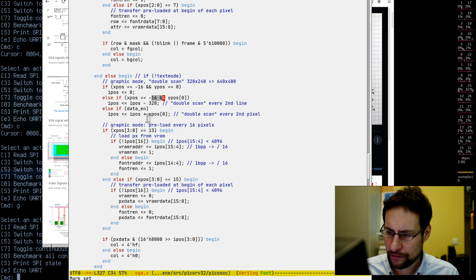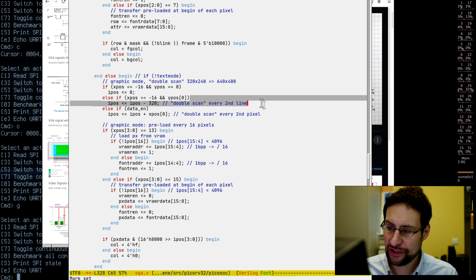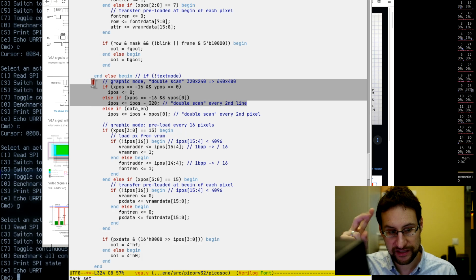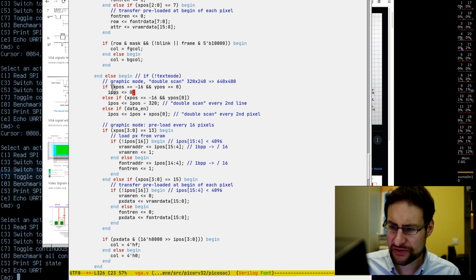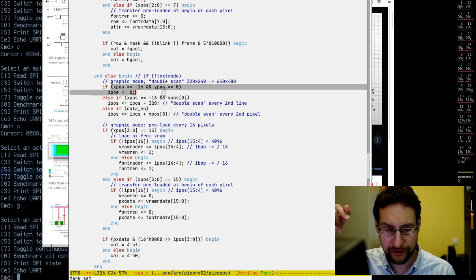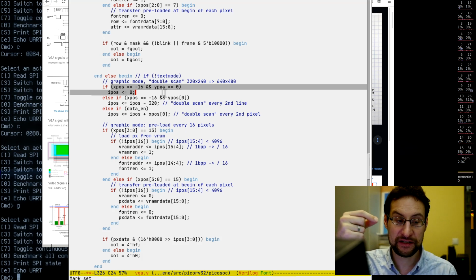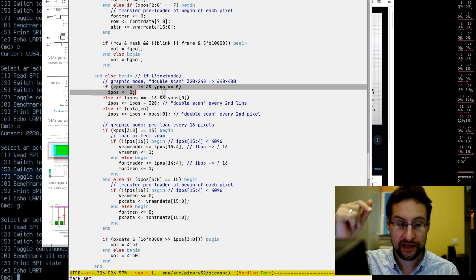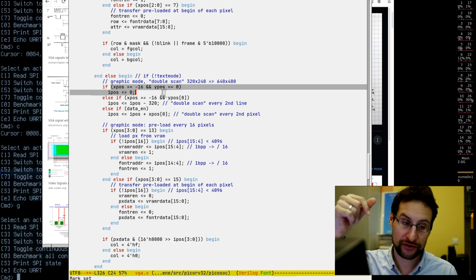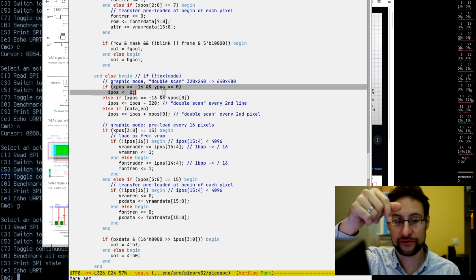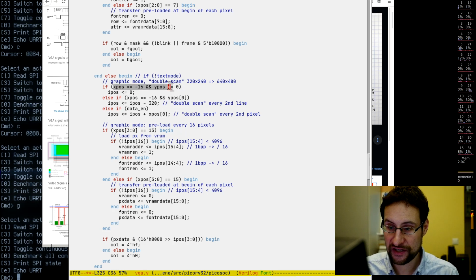Why do I have this here? All right, and this is only a little bit complicated due to double scan lining. So similar to VGA hardware, we are duplicating our lines. We need to reset our linear frame buffer position before the first pixel, because again, with the memory load delay, we need to have this address before the first pixel. So this address needs to start at a negative offset before the first pixel at 0. And this is why I preload this at -16,1 and reset this.